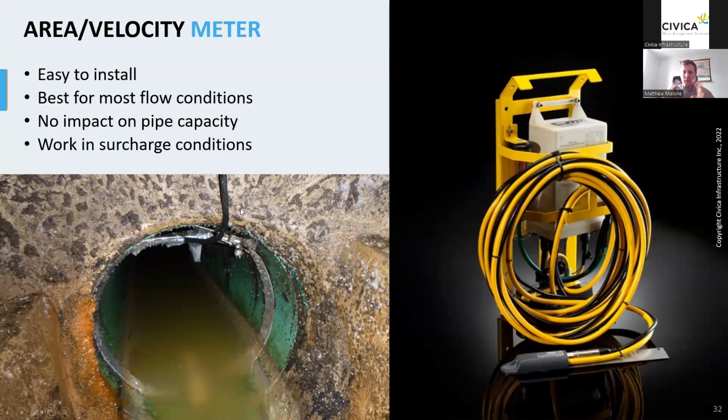It doesn't take up a lot of space in the pipe, which is great, so you're not backing things up. And they work in surcharge conditions. Most of these sensors are still measuring velocity. A lot of them can record negative velocities, so if the system backs up and the flow starts going the other way, and they can measure pressure, depth up to 3 to 5+ meters. So when this system gets overflowed, you can see that in the data from a lot of these different types of AV sensors.